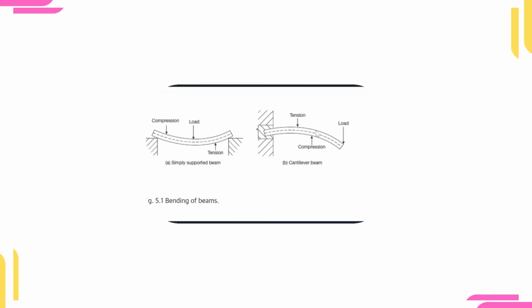And if it is not properly reinforced, it will fail from this tension zone because concrete is generally weak in tension and very good in compression. This compression zone will not fail, but as a result of this tension zone failing, this compression zone will also fail.